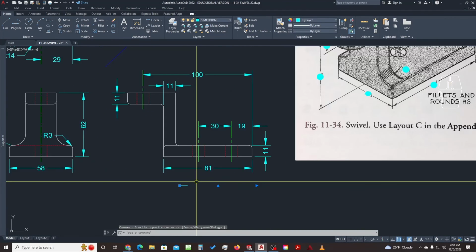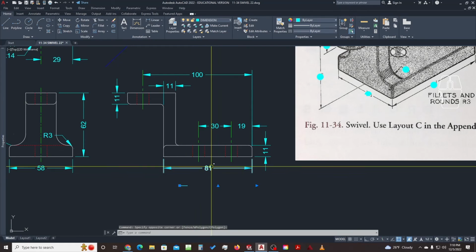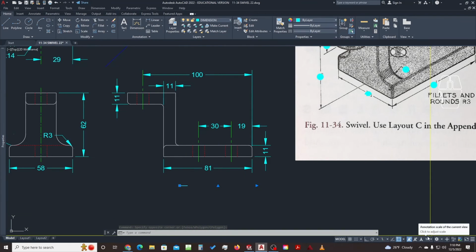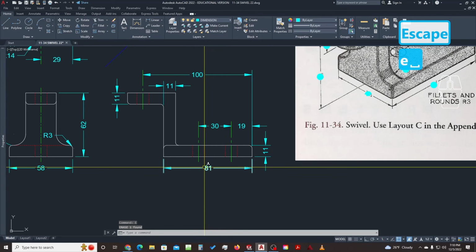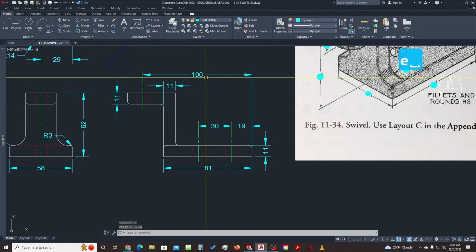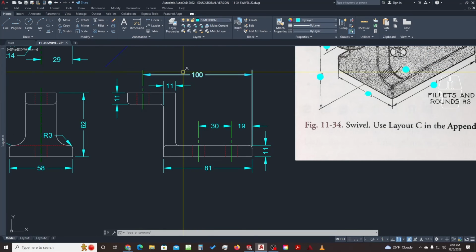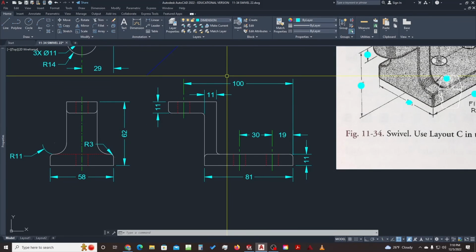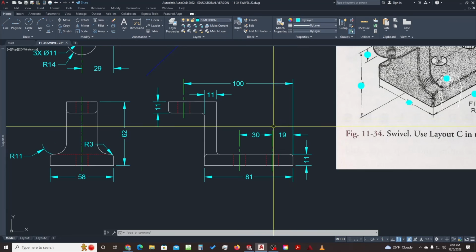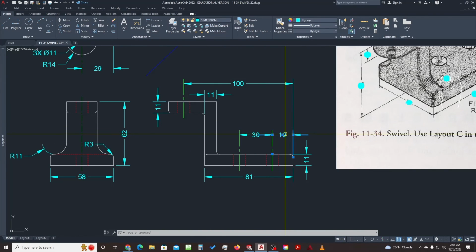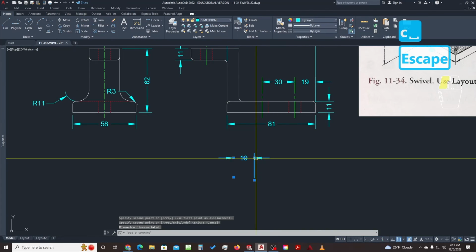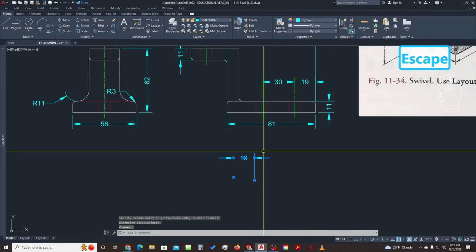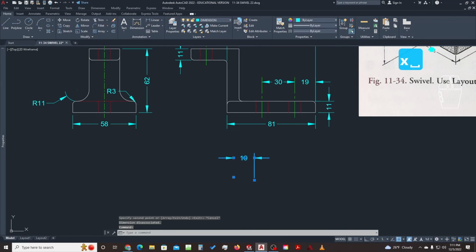So rather than fighting with scale and trying to get the size to match this 1:2 scale, we're going to use a different option, which is just copying out of a dimension. So good that we saw how not to do it. Anyway, grab any dimension that's going horizontal. Let's grab it, copy it, and pull it down. And then we're going to click on it again and hit the X key for explode.